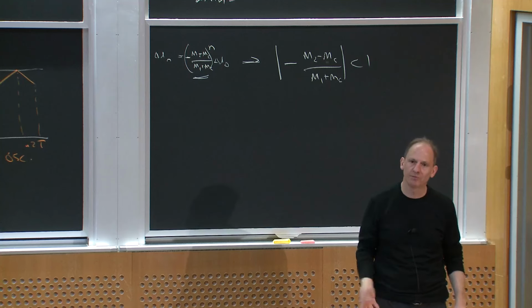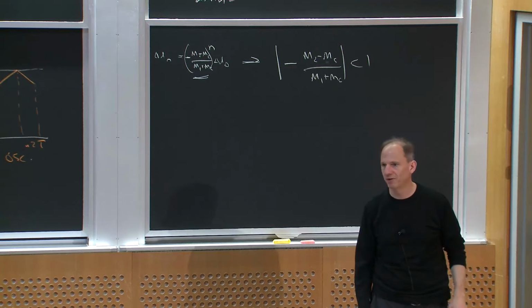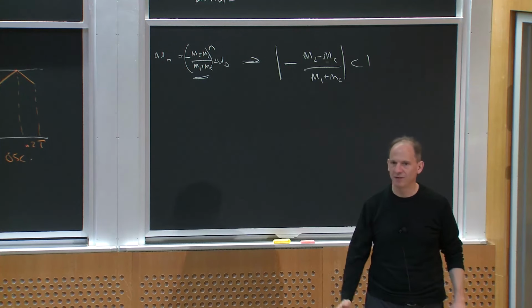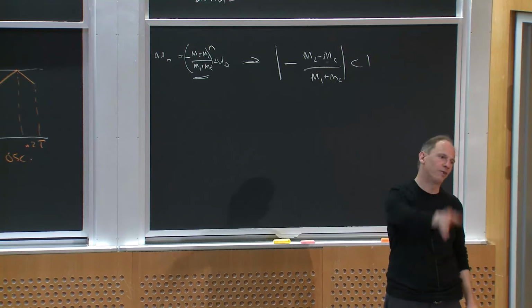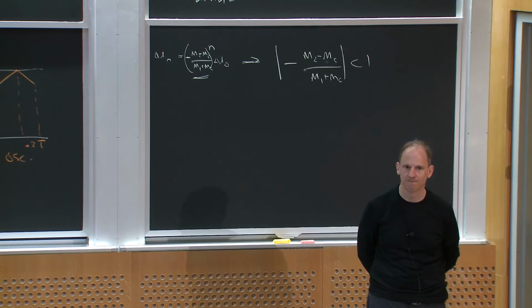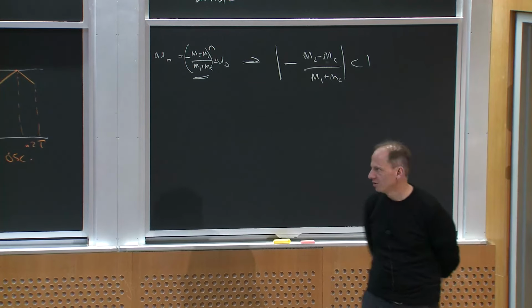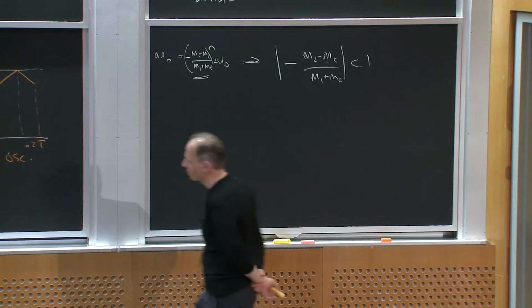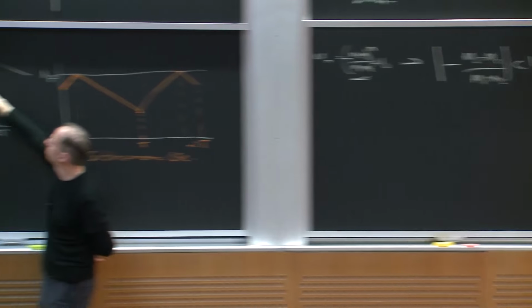So if you took a boost converter and you didn't put in any slope compensation, if you're only running a 25% duty ratio, fine, you won't have any ripple instability because it'll settle down. If you get near 50% duty ratio and above, it'll start doing this subharmonic oscillation or ripple instability stuff. Okay? This is sometimes called the compensating ramp or the stabilizing ramp for that reason.